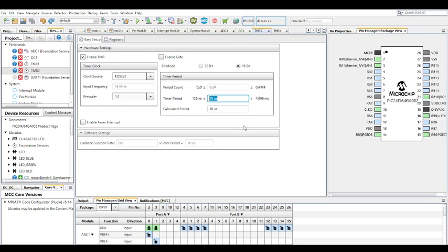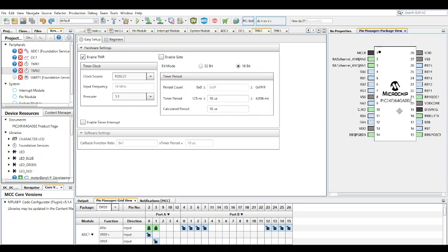Personally, I'd go above 60 kilohertz, at least 75, but 100 kilohertz is a sweet spot. And if you design your PCB decently, it should function just fine with 100 kilohertz. With 60 kilohertz and below, you have to have bigger components on your board, and your control suffers for it. You don't have a lot of flexibility control-wise.